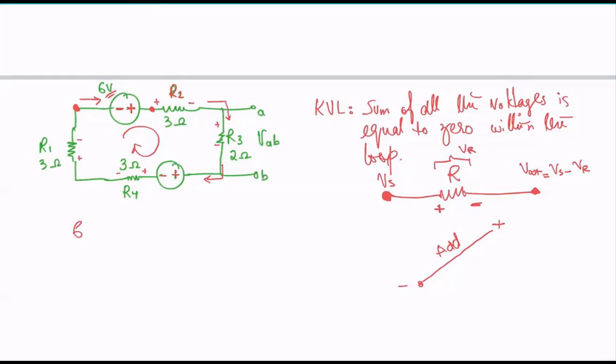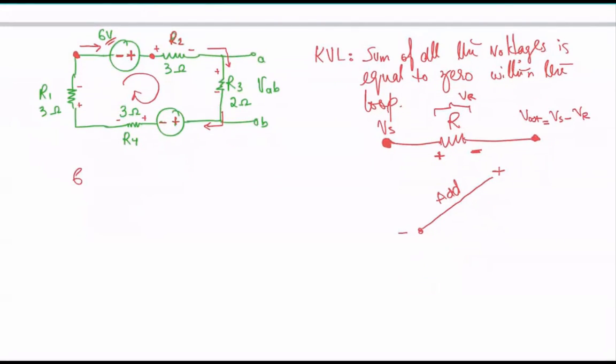So voltage drop is going to be considered as you are climbing down the hill. So basically you will go down. So you have positive here and you have negative here. When that's the case, you subtract the values, okay? Correct? Okay, so 6 minus, what is the voltage across this R2? Say this is a series circuit, so there's only one current here, because in a series circuit, current remains the same, and I'm just going to label it as I, and I can simply apply Ohm's law to find out the voltage across the resistor, which will be I times R2, right?